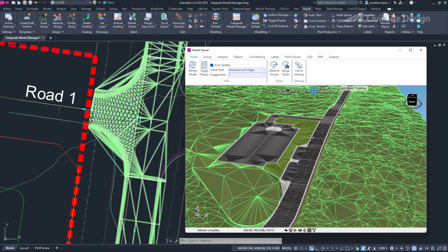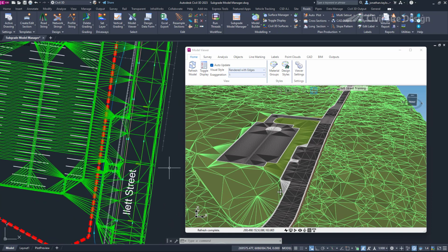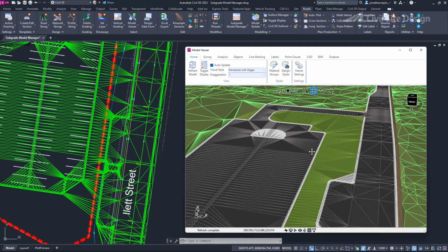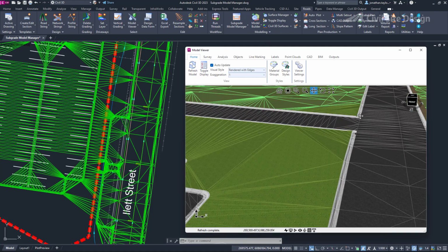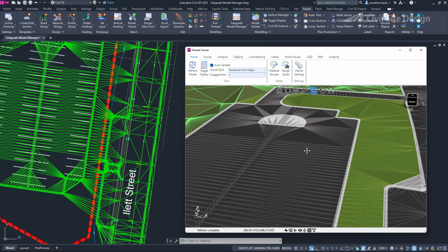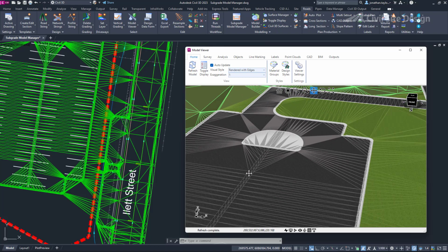we've also got some independent string design, namely the parking bay, which is being displayed down here. So this is an independent string. We've used Model Builder to cut the road out of this particular part of the design. We've also got an entirely separate car park where we have made sure the elevations are tying into the road at the start, but the design of this car park is completely independent. We've also got an island represented in there and a dish.